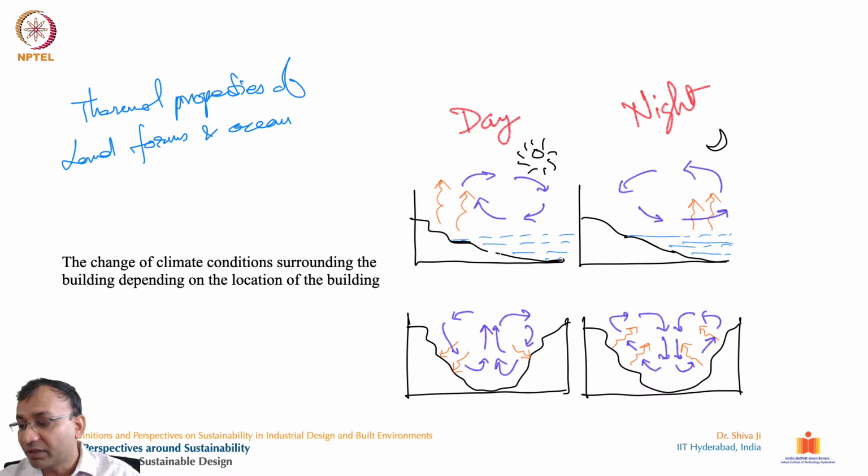In the daytime, the hot air is rising from here in the middle, and in the night time the hot air is rising along the surface of this valley. So it's completely opposite in these two scenarios. We must have an understanding of the topography, geography, and climate of any place, and the orientation of the sun and prevailing wind directions for planning our building. This is one of the strategies we employ right at the beginning of building design, at the concept stage and the design guidelines stage.